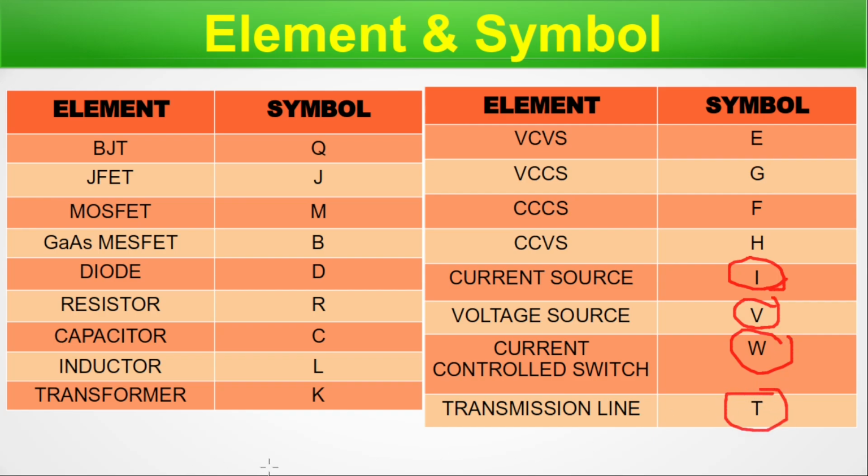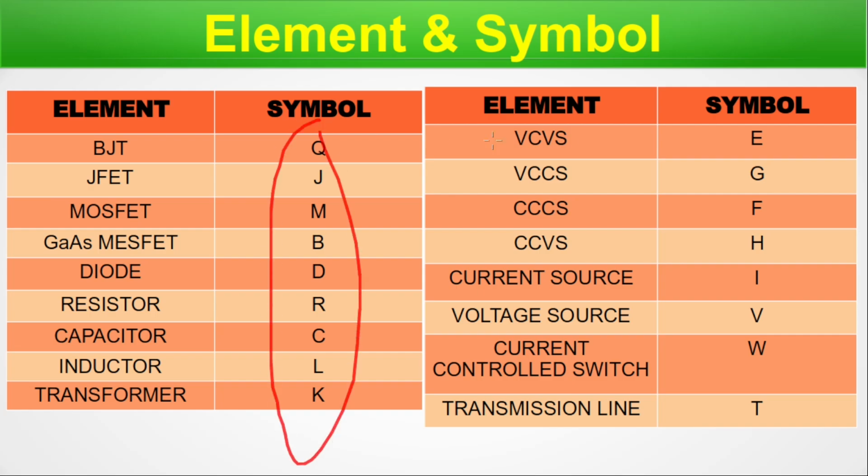So this is like when we are writing a SPICE deck, there will be some lines that begin with, say, voltage source or the current source. So it will be I, say IDC we write, or I10 or I5, something like that we write, and for voltage we write similarly like VDC, VDD, all these things we'll write. These are used as the first character of the line. So these are the first characters of any line that you write in a SPICE netlist for the components. So we are done here. Let's move on to the next slide.